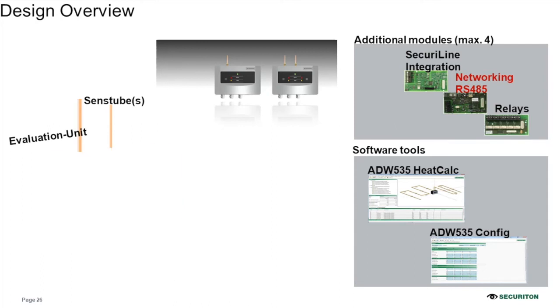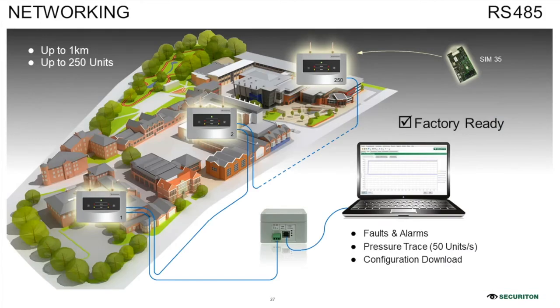With that, I'll go to the networking, which is one of the questions raised earlier, whereby we can use the LAN itself, or you can also convert the LAN connections into a fiber and reconvert, and you can view this in a central place. And you can also recommission the system from the central place. You don't need to climb up the roof tank to look into what the problem is, so you can get most of the information. Only for troubleshooting do you have to go to the floating roof tank on top of the roof. So all this information can be retrieved from a central station.